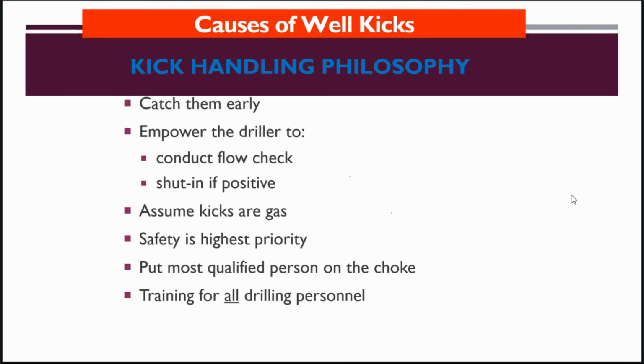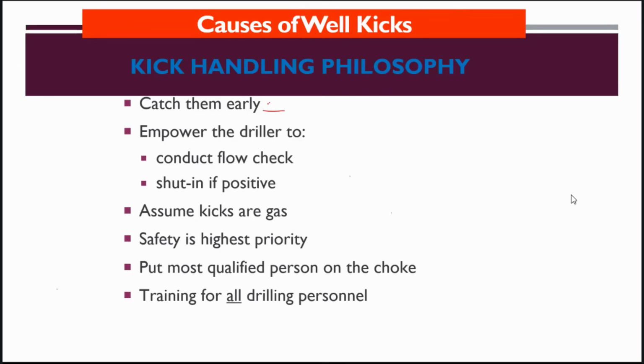So your philosophy to handle a kick is to catch it early. Why catch it early? If you catch it early, the volume of the kick will be less. If the volume of the kick is less, it is easy to handle and circulate out. The driller should be able to conduct a flow check.